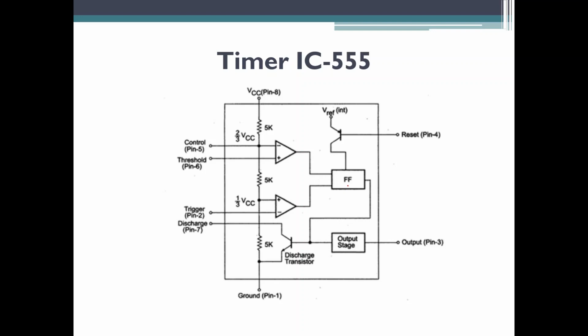And also you can see there is one more transistor which is connected, which basically works as a reset. Reset in the sense, if you want your flip-flop to be reset, if you want it to be cleared. You would have studied, a flip-flop normally will be having a clear and reset pin, right? So if you want the output of the flip-flop to be set to 0, you can set this particular pin. That is actually done via the reset transistor connected to the flip-flop.